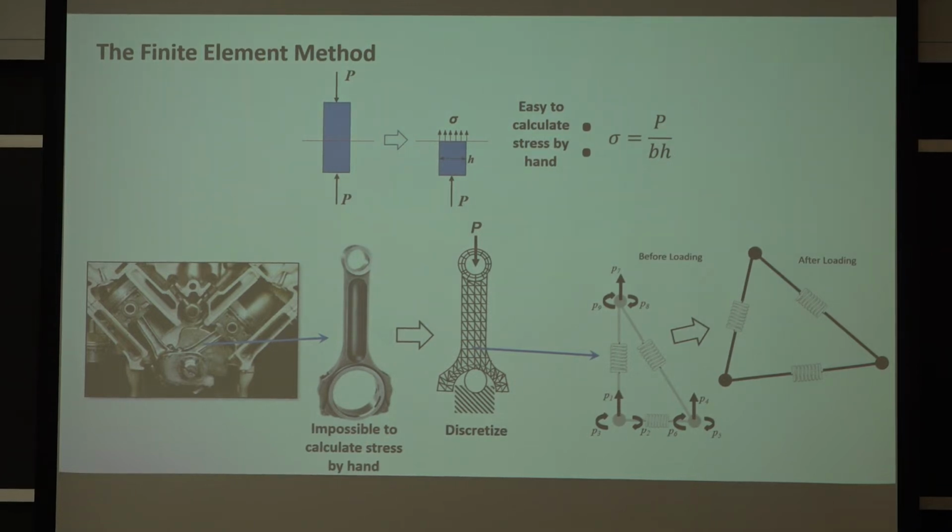Having said that, the way a finite element calculation works is that you take your complex geometry, you draw it up in CAD world. Don't bend it, Paige. Okay. You break it up into little elements. That's called discretizing the volume. And then you can think of each of these little elements in computer land as little parallelepipeds or little plates or little beams that can be approximated by a series of springs.